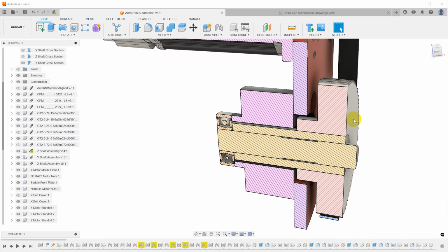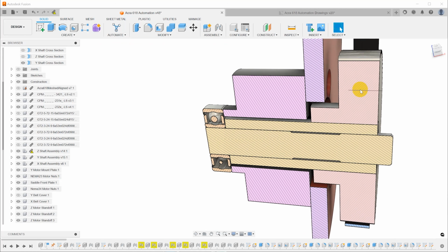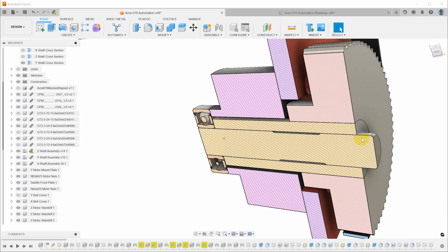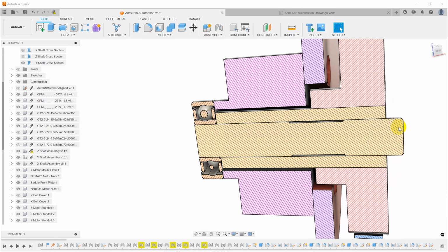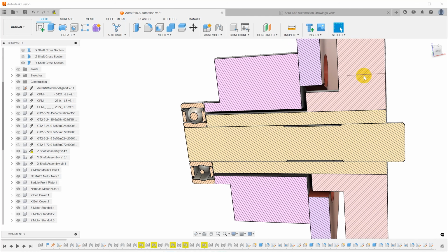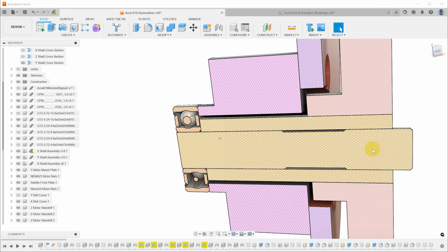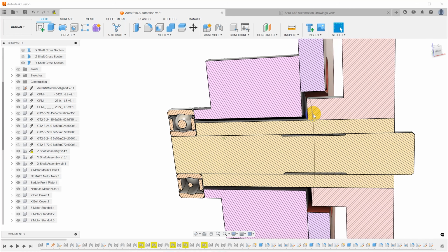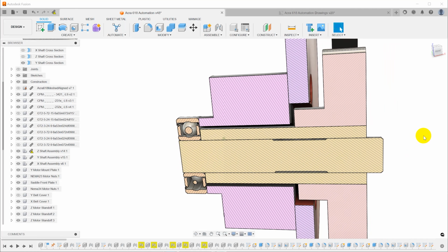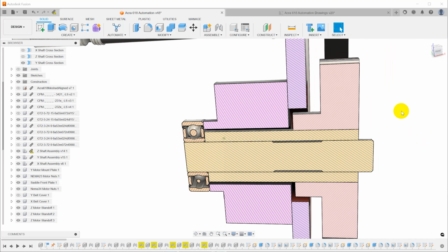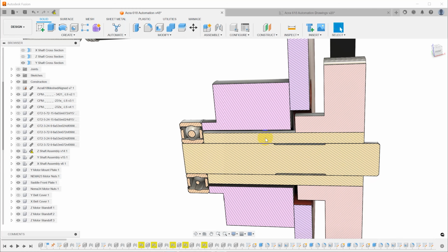the pulley to. Now we could have just bored the pulley to match this shaft. The problem is that only one side of that pulley would bear on the full diameter of the shaft, and the side over here with the set screws would be over this gap. And that would probably work if the fit was really close, but those set screws are going to try to push the pulley off center, and since the edge of the pulley can move into that gap, it's not going to stay straight. So I would like to have this adapter bridge all the way over that, and we might as well go all the way to the bearing race just like the original hand wheel.